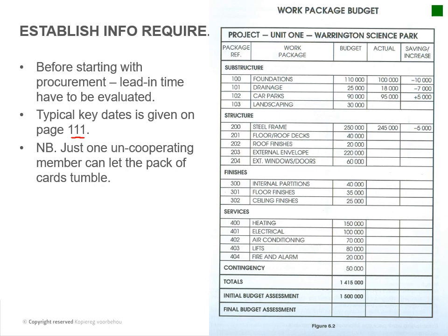So what will happen is, for instance, you've got your subcontractor that's going to look at your foundations. You've established your budget, and you've established that you're going to remeasure all of the work. You've got some standard rates that you will apply, for instance your excavations and so on, but the quantities aren't final yet. So during the actual work, you measure your actual quantities and you try and show a saving there.